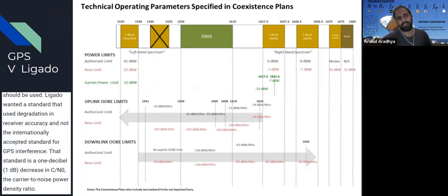So our idea with this is if we can establish traceable measurements. We're in Boulder, so everybody should actually know the phrase NIST traceable, because that's what NIST does, and it's right here. You establish certain standards and certain methods of measurement, and then you tailor every other measuring device to that particular standard. So in our case, it would be tailoring the voltage and the power that we actually measure through our antennas to something that's measured at NIST and says this is the absolute radiometric brightness or the absolute power that's transmitted at a certain frequency.